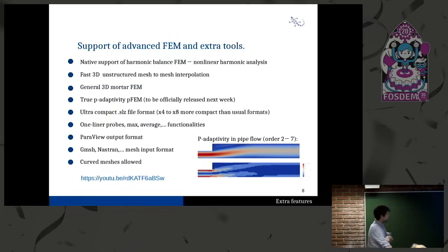Basically, I started writing this a month ago, and it will be available next week: p-adaptivity. So you can change the interpolation order on every element in the mesh, which means only on the elements that actually require more computation will you perform more computation.